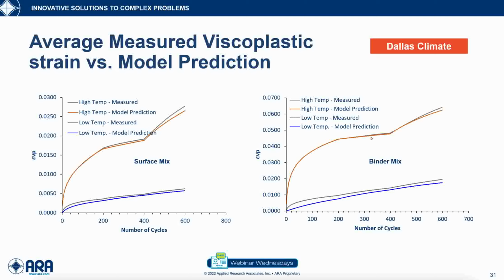And that tells me that the SSR test with the shift model are predicting the viscoplastic strain correctly, similar to what the specimens are being deformed by. So that gives us power and confidence with the SSR test and the shift model that they are predicting the correct viscoplastic strain for mixes under certain loading conditions, certain temperatures, and certain frequencies in loading.